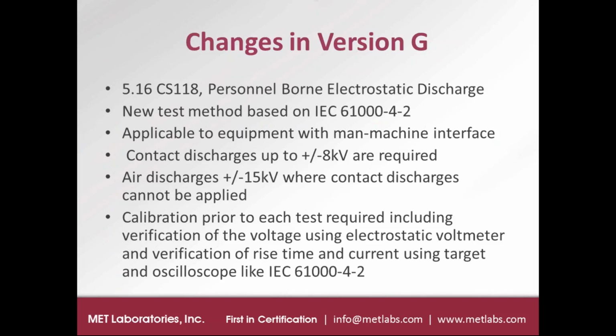CS118, they call it personnel-borne ESD discharge. That means that when we're doing this test, we're simulating the same type of discharge that everyone might have experienced on a cold, dry day. You go to open your car, you get a shock from the metal chassis of your car. That's an electrostatic discharge because your body has a different potential compared to the chassis of the car.